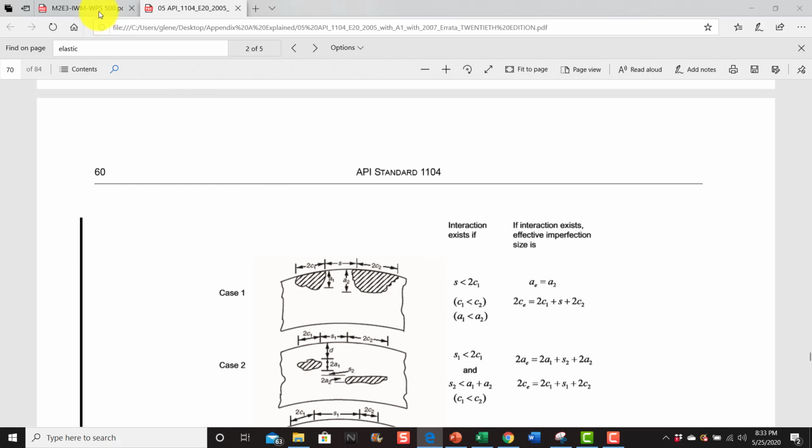But like I said, always understand your procedures. Read your procedure, weld procedure specification, and make sure you read your notes, because you may be inspecting by workmanship when you should be inspecting by Appendix A. And that Appendix A allows more leeway, so it's more generous.